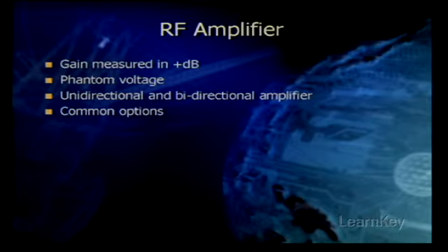Keep in mind that your amplifier must be connected to the network with all of the other radio frequency devices. So make sure that your amplifier has the same kinds of connectors as the cables and antennas that it's going to be connected to. Typically, your radio frequency amplifiers will have either SMA or N-type connectors. Both of these perform well and are widely used by most different devices in the radio frequency realm.